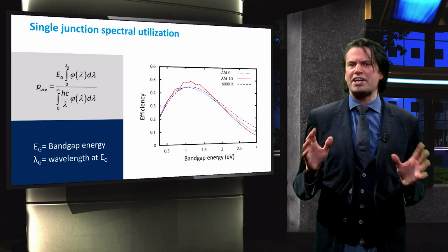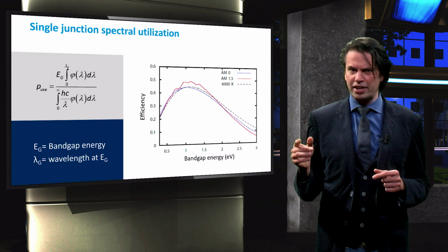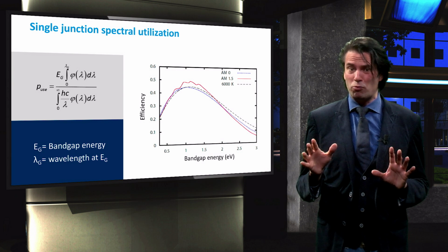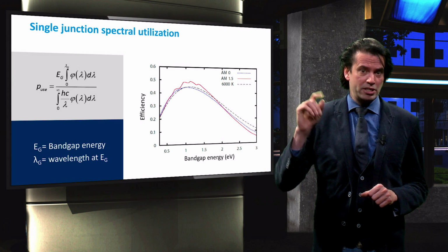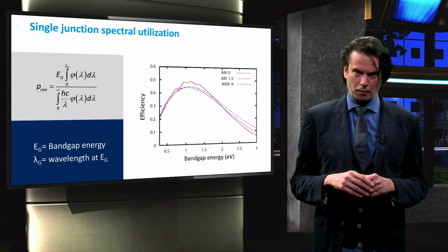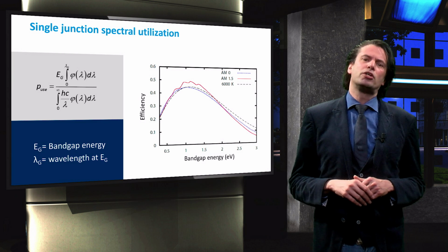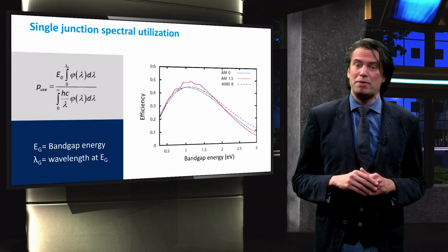Naturally, the usable fraction depends on the irradiance characteristics. Therefore, it differs slightly between the AM1.5 spectrum on Earth, the AM0 spectrum in space, and the spectrum of a perfect black body radiator. The trade-off between thermal relaxation and non-absorption defines an optimal band gap energy.